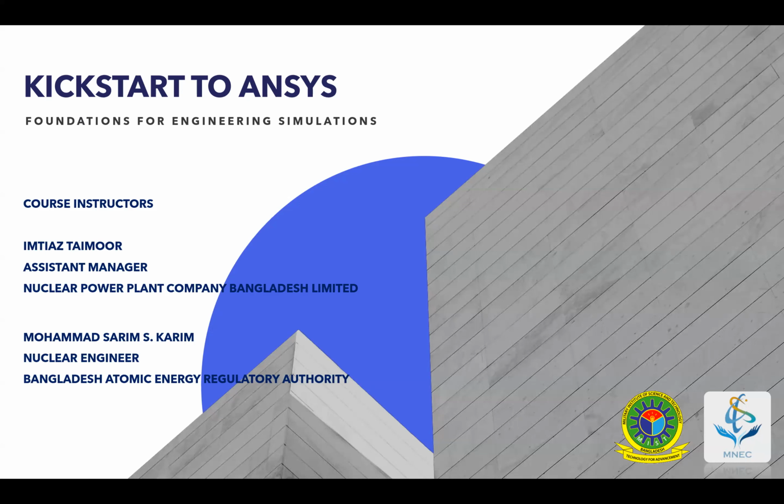It is mainly needed for thermal hydraulics analysis. Let us suppose we want to analyze the velocity profile in a hot leg pipe. Then we can construct a pipe in ANSYS, then add water as the fluid, then run the simulation. We can get the velocity profile of water, and thus the velocity of water flow in each layer. After getting this data, we can calculate the heat transfer coefficient, Nusselt number, etc., from mathematical formulas.